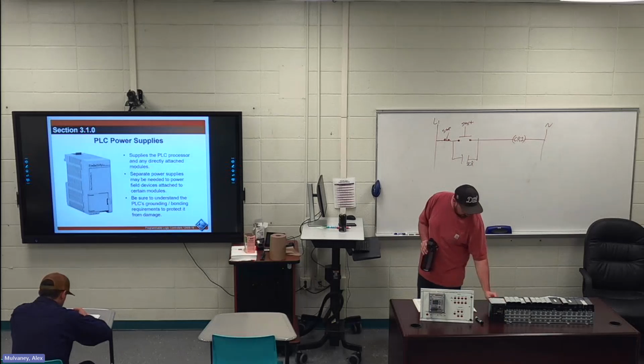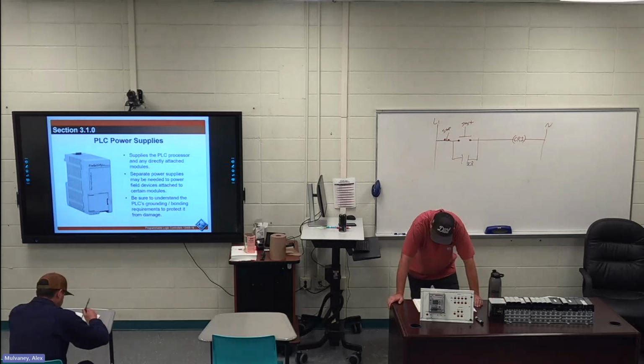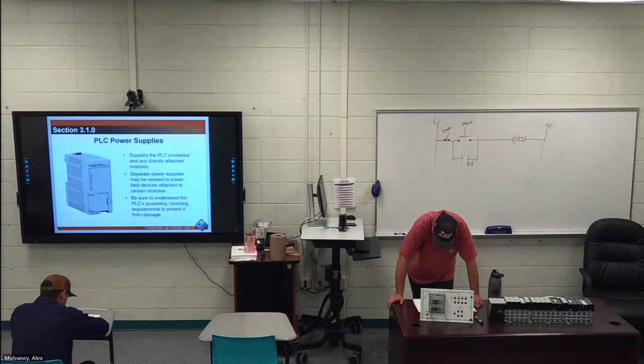Processor scans, I have the beginning of the paragraph through the word scan highlighted. The processor module controls the system by executing the control program. During program execution, the processor reads all the inputs, evaluates and acts upon them according to the program logic, and then modifies any outputs affected. This process of reading inputs, executing the program, and updating the outputs is known as a scan.